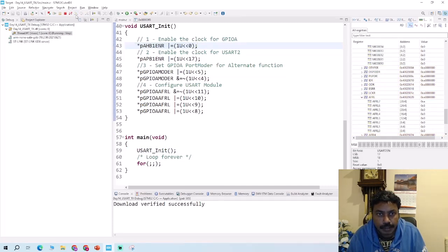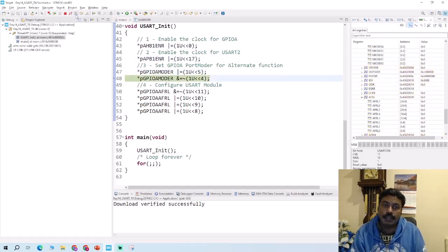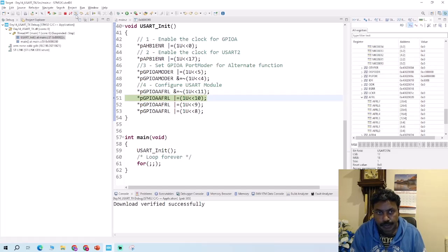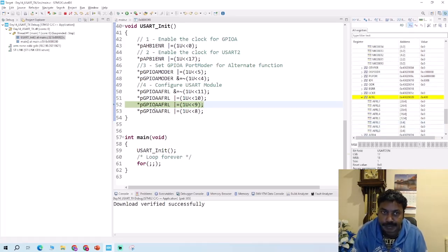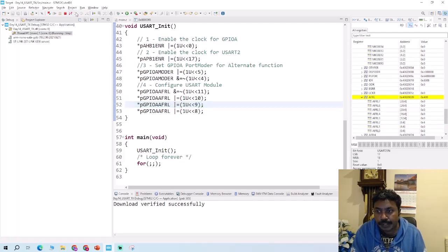And enable, and now the peripheral bus. Now it's going to set the mode. Now it's coming into the alternate function register low. So just pay attention to AFRL 2, and see what happens at the end of all these 4 bits. So see, it has already changed to binary value 4. So what is that in decimal value? Now it has changed to 100, but we haven't finished, as it's only a step into. So we need a 7. So now it's 6.